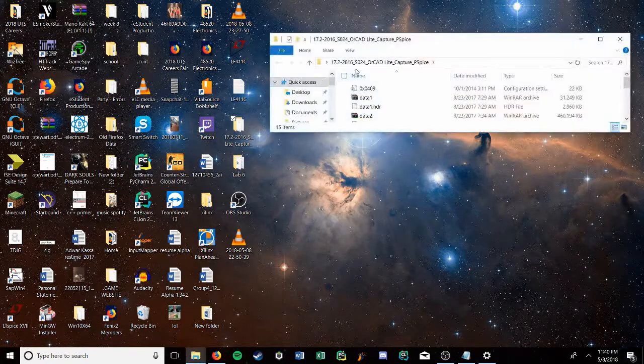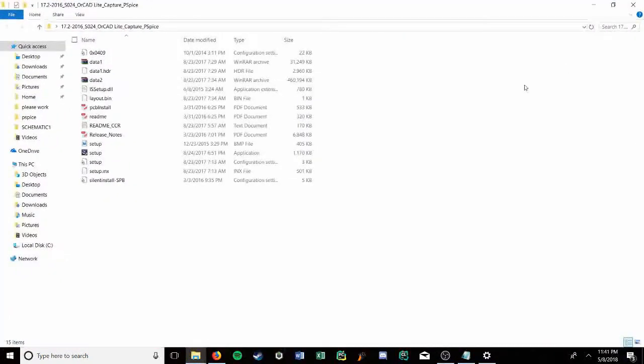Once you get that file, you just have to unzip it and open up the setup file. I'll just go through it, but there's one thing I cannot stress enough. There is a prompt that will ask you to install it for either the entire computer or just one specific user, for only the current user. Make sure you only do the current user, because if you do it for all the users, you'll never get a simulation to run. It's some weird kind of bug. I had to actually reinstall to get it to work.